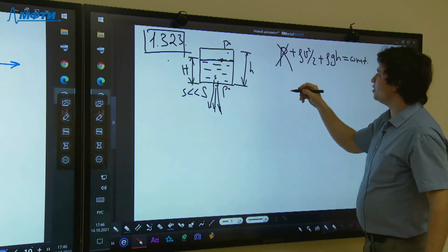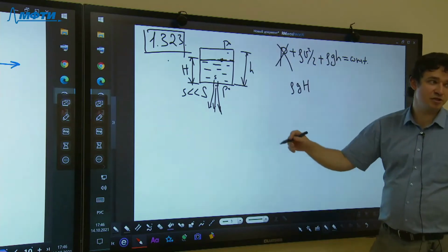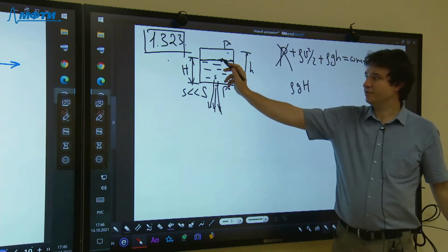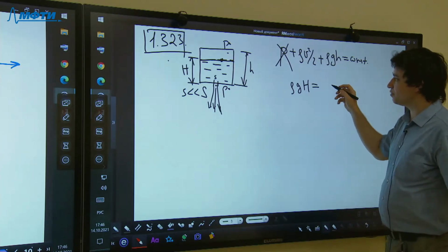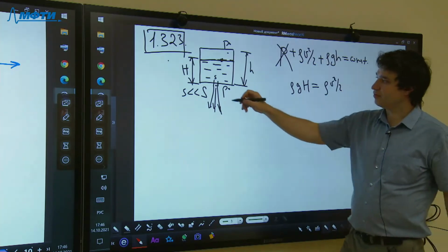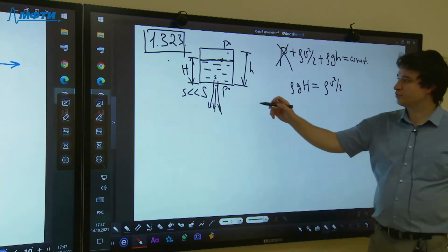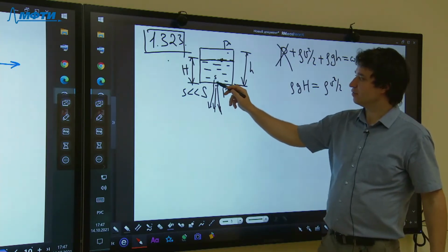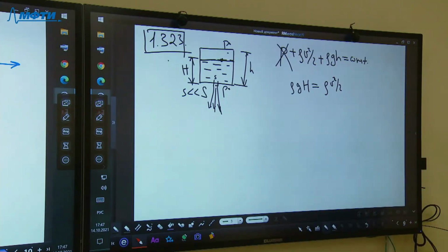So that would give me rho g capital H and almost no velocity. Since in here, there would be almost no motion of liquid. That should be equal to approximately rho v squared over 2, where v is the speed of the water which flows through the orifice. And as I have said, according to Bernoulli's equation, this velocity is uniform across the cross-section of the orifice.